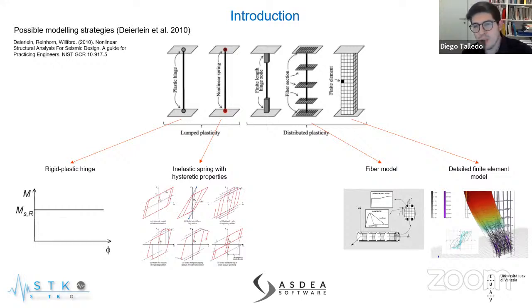Actually, fiber sections are not required for distributed plasticity. We can also have moment curvature constitutive laws in several Gauss points along the member. But anyhow, in its most common implementation, that is the fiber discretization of the cross section, we perform numerical integration through the member cross-section in order to obtain the constitutive moment curvature relation, and along the member length, so permitting the spread of the inelasticity.